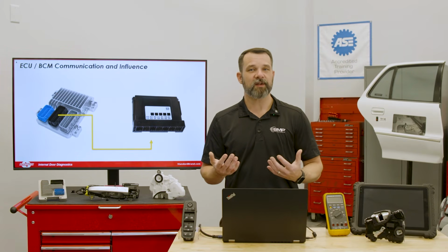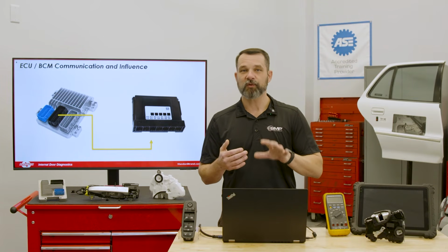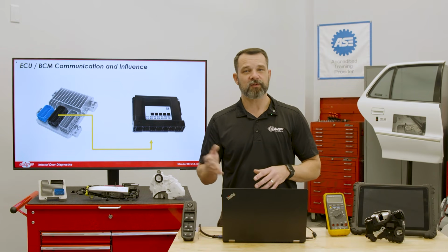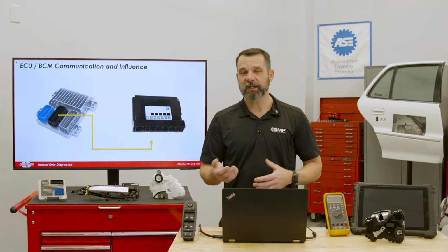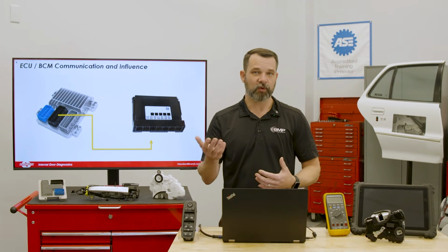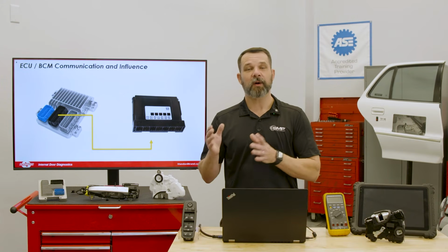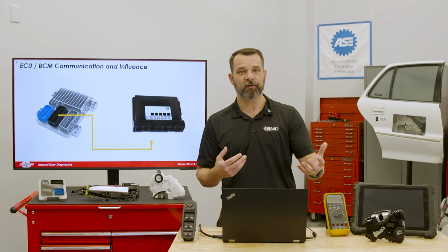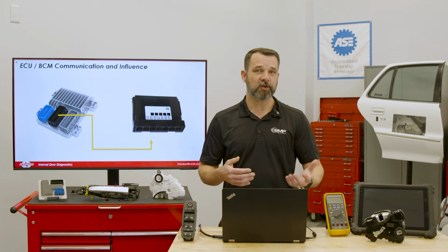And we also have to consider things like crash detection and door ajar signals. The BCM actually provides door ajar state to the ECU, and then the ECU uses that information to adjust things like idle behavior, high voltage shutdown in electric vehicles, and EV drive inhibit when the door is open. And then there's also load management to consider, because the body control module reports things like electrical loads running from window motors. And the ECU can then use that information to adjust idle speed or even charging output.